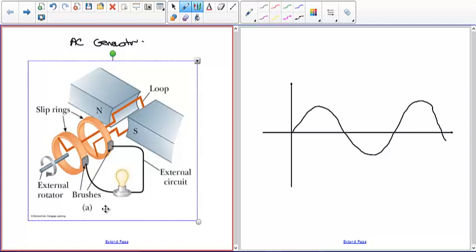That's going to be 60 cycles per second, or 60 hertz. So I guess it could probably rotate at 7,200 RPM, but I think usually they rotate at 3,600 RPM. And that's how you get that. In Europe, where they're using 50 hertz, they're probably rotating at 3,000 RPM instead of 3,600 RPM.